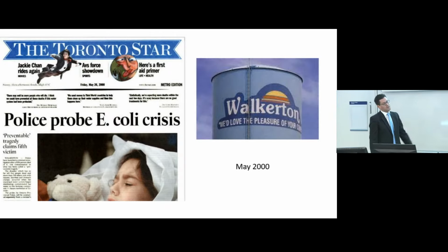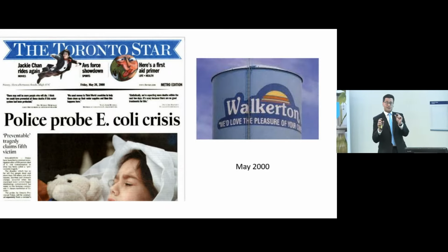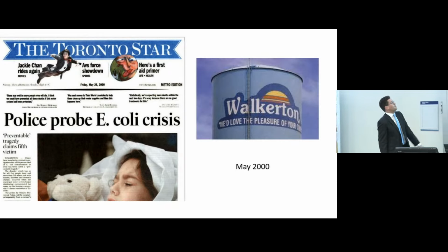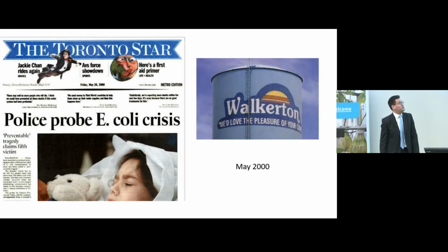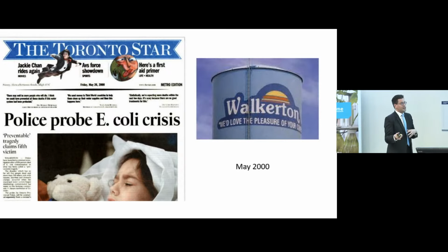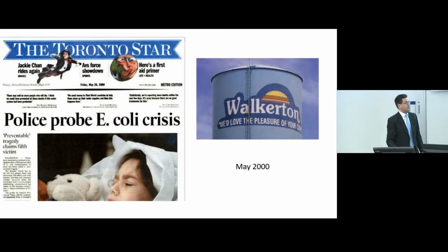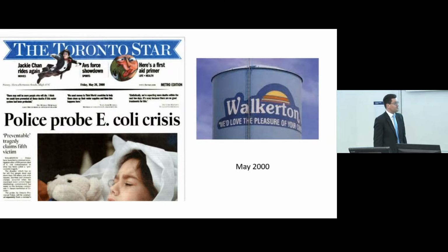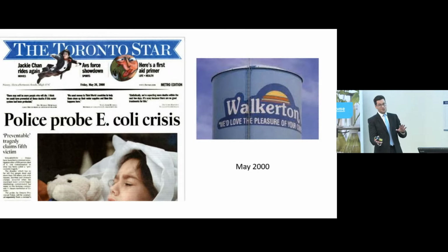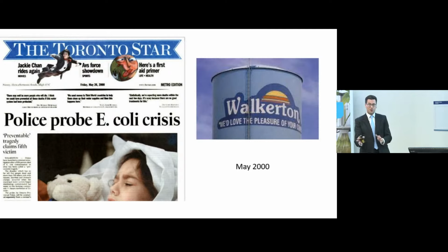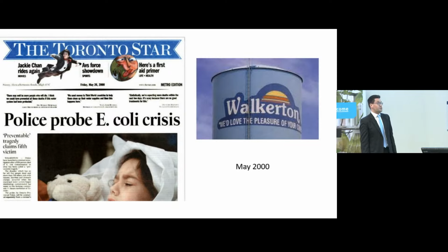The picture there is from my PhD thesis, where I was taking electron microscope pictures of different types of viruses that I was using in my research. Different shapes, some of them the round-shaped one there, which was quite a small one, and then ones with tails on the end of them, which were about an order of magnitude bigger. I tried to understand what particle characteristics and virus characteristics lead to protection of these viruses from disinfection. And one of the recommendations that came out of that research was that you really have to do a good job of removing as many of the particles as possible before you disinfect the water, and also that certain types of particles are particularly problematic if you're trying to disinfect water.